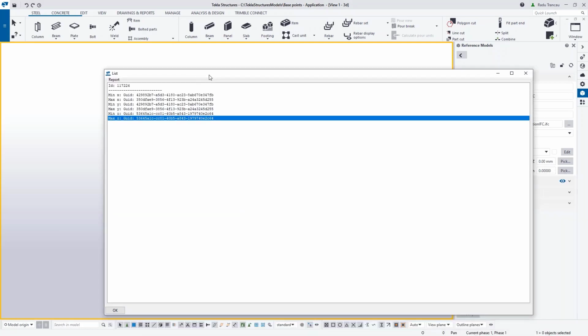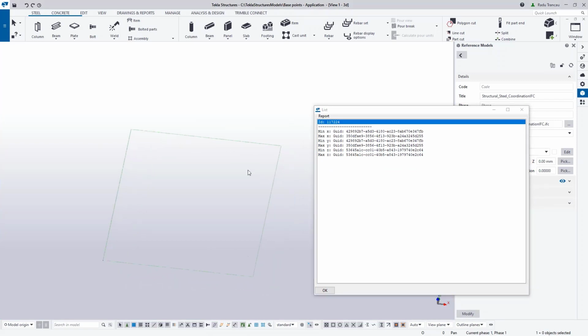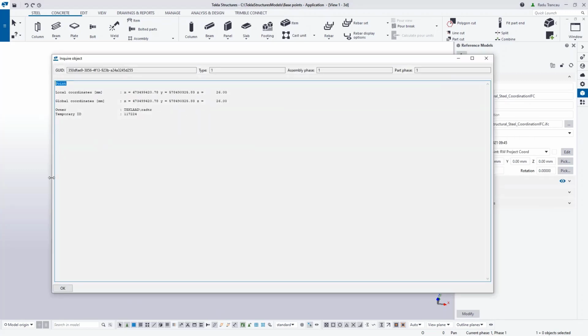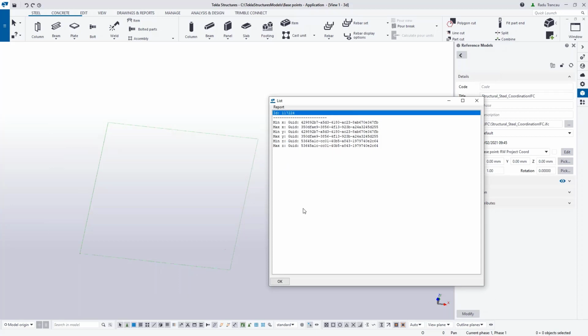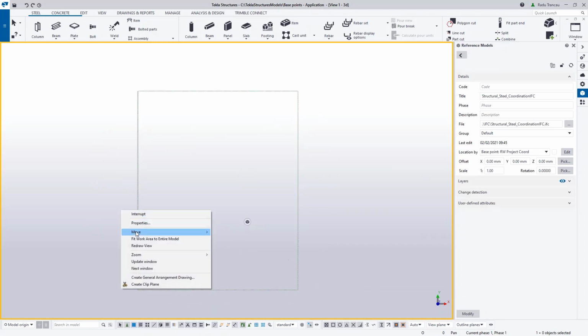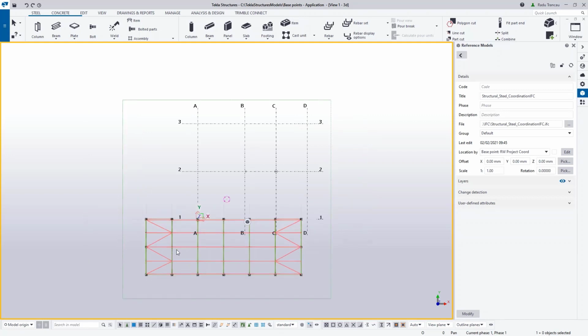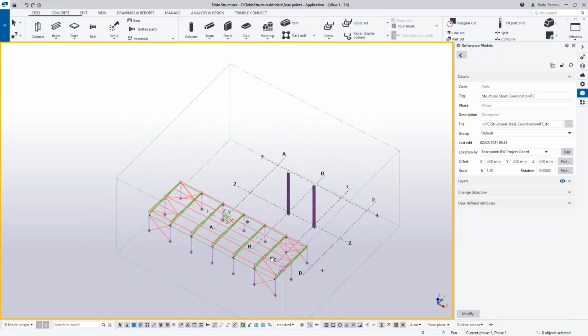Find Distant Objects. Okay, so you should get a window with a point, right? So that is the point that I've just missed in that corner, and I wish it to be deleted. You can just inquire the object and you will find what it is in here. So quick way, go here, right click, delete, and that should clear the problem for the next fit work area to entire model. Okay, that's a very simple solution to a very common problem that we've seen.